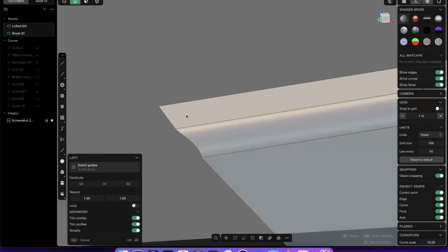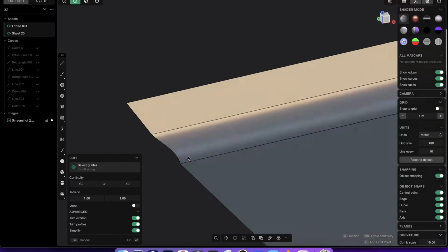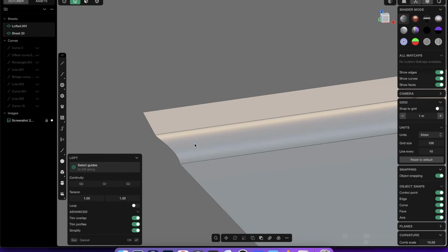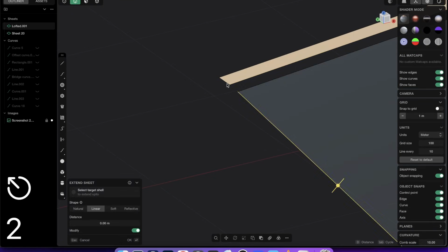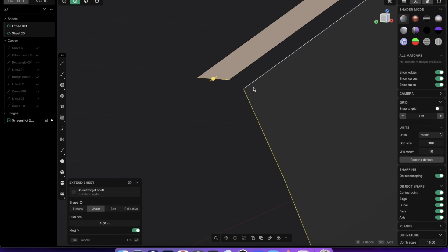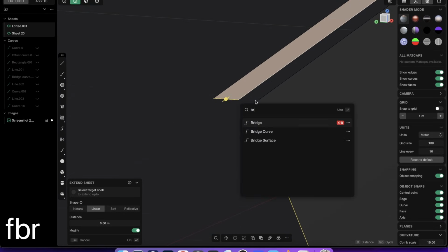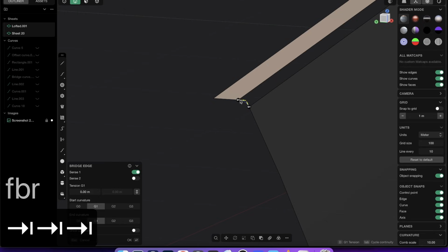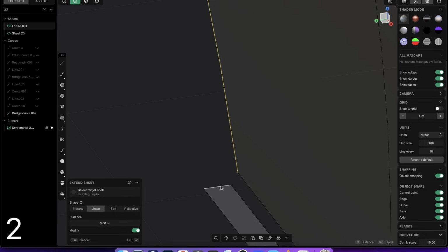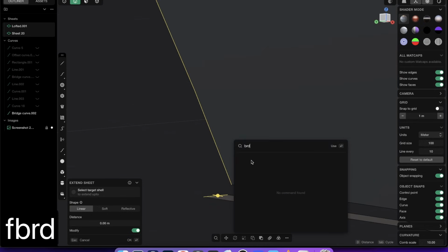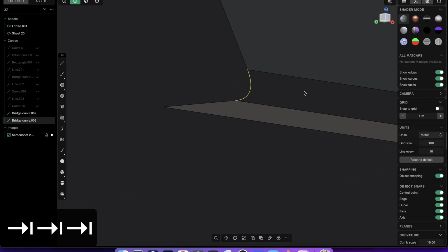You see this fillet has a weird ending here, right? So it's not smoothly connecting those two edges. For that, a very simple trick. So before you loft that, first loft those edges or bridge them. So just select those edges here at the front and F and bridge and tap, tap, tap. Just leave it as G1 so you just have a curve. Do exactly the same at the bottom. Select this edge and this edge. Press F and select bridge. Tap, tap, tap. So it's just G1.